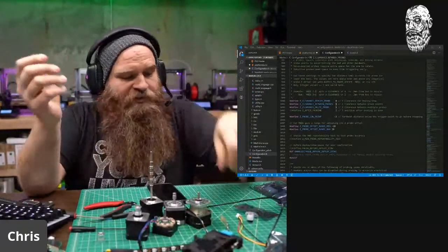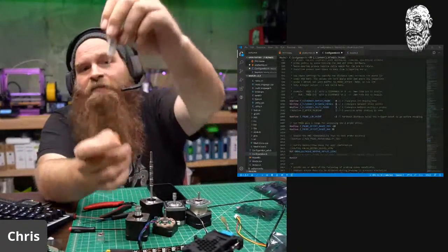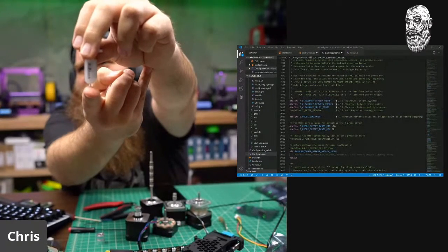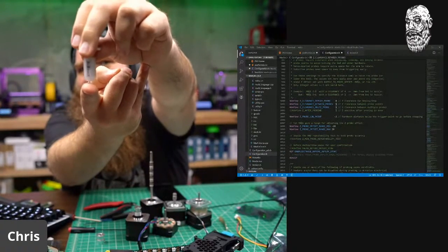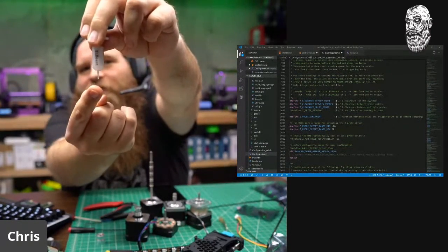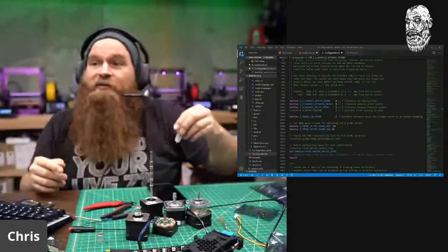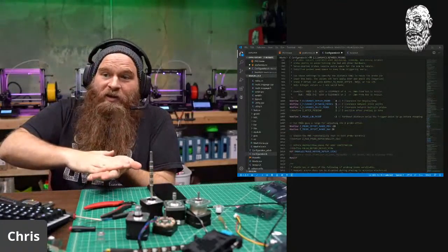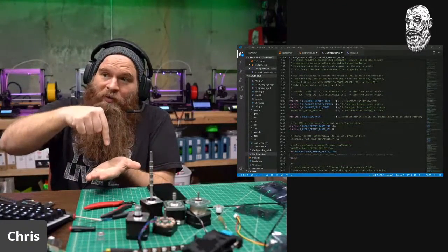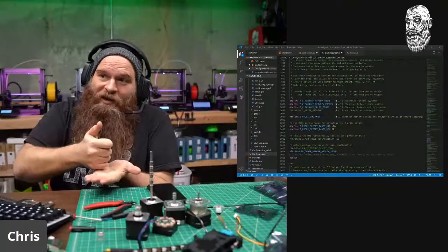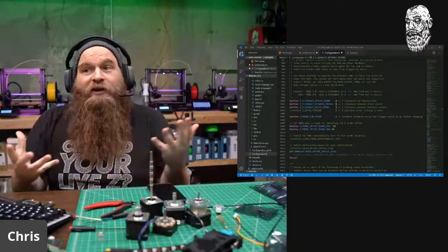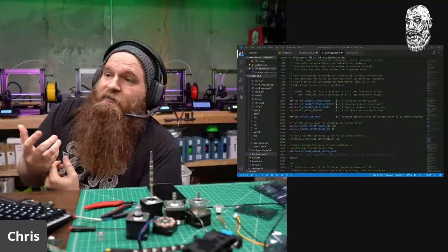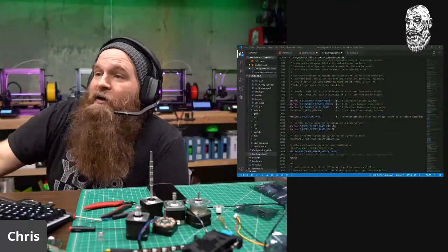Something like the BL Touch is different because the BL Touch has a stick that comes out, and then when you probe the bed, the stick goes back in, and then it needs to move up and then deploy again and then probe again. So that distance is like 5 or 6 millimeters. So typically we put a value of 5 there. So it goes down, comes back up 5, drops the probe, probes again. The probe goes inside, it moves up 5 millimeters, releases the probe.